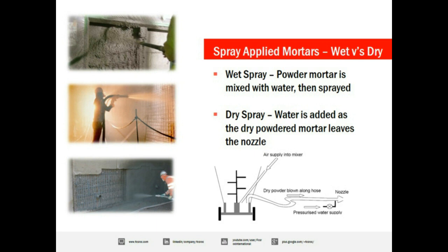But to give you a bit of an idea as to the difference between hand applied and spray mortars, and the kind of efficiencies that you can make with them. If you look at the thumbnail in the bottom left hand side there, that's an area that's maybe so high, 1.5 meters in length. To do that, a 2-person team doing that by hand would probably be there for a couple of days, to be honest. The difference with a 2-person team doing this with a dry spray or even with a wet spray, you could do that in about an hour. And that's a massive difference in the time it takes to reinstate that amount of concrete.